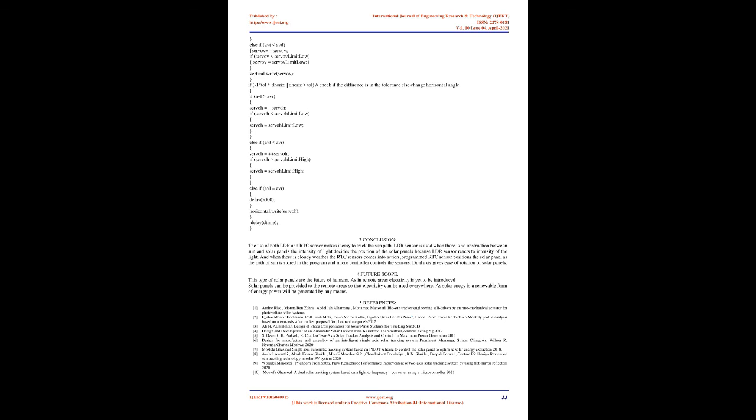If one of the LDRs in a pair gets more light intensity than the other, a difference will occur in node voltages sent to the respective Arduino channel to take necessary action. The DC motor will move the solar panel to the position of the high-intensity LDR as was set in the programming.